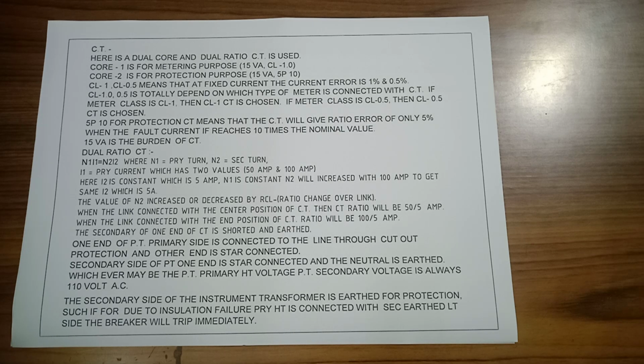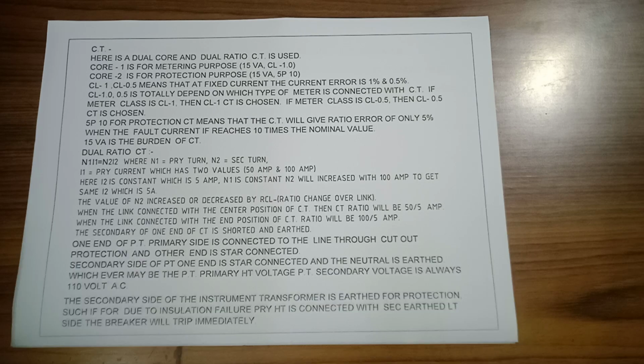Okay, next. CT secondary wiring to be 1100 volt grade 2.5 square mm black PVC insulated multi-stranded copper flexible wire.